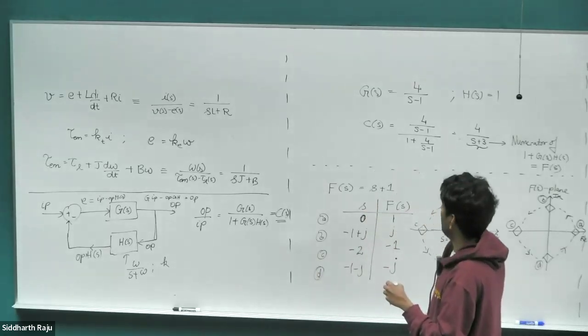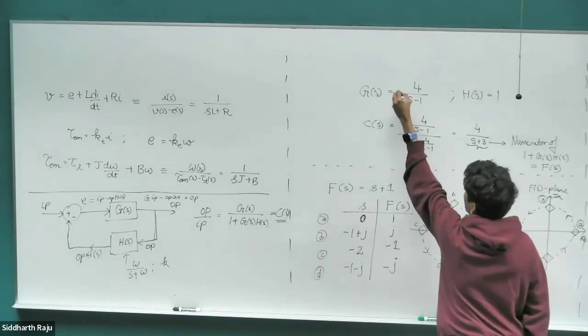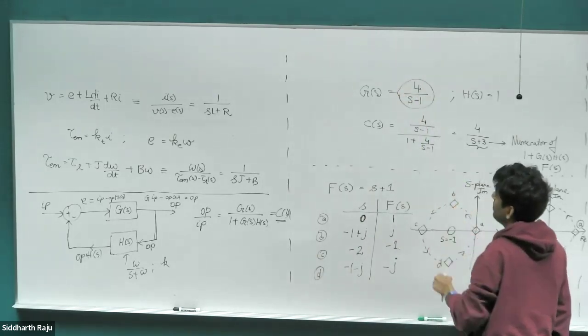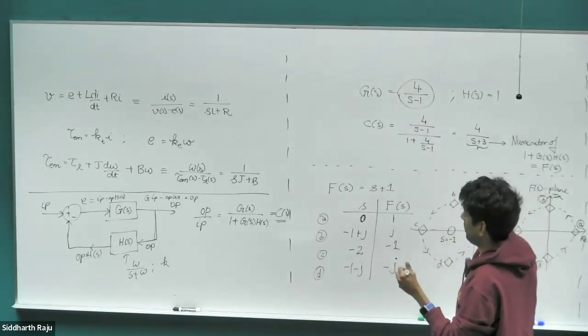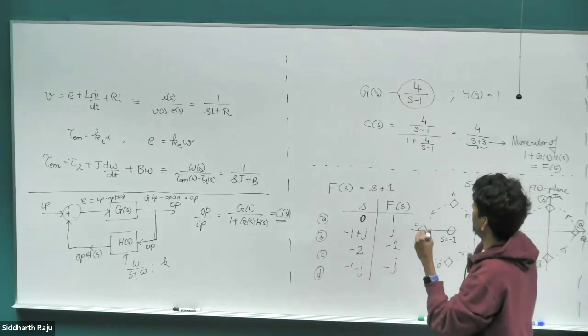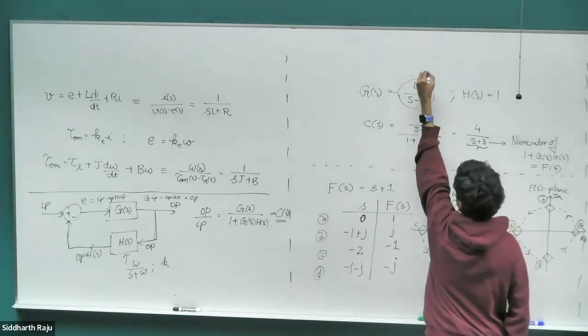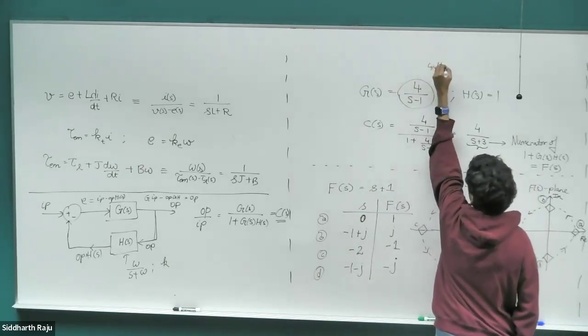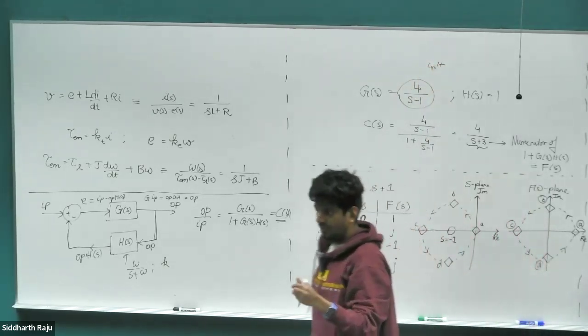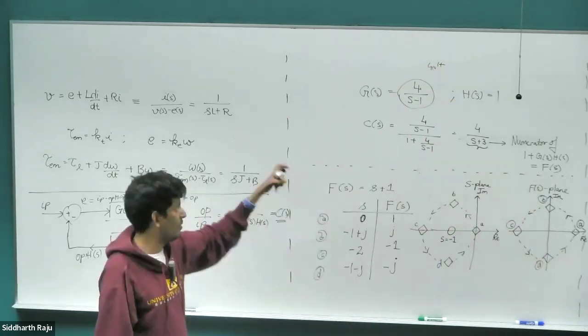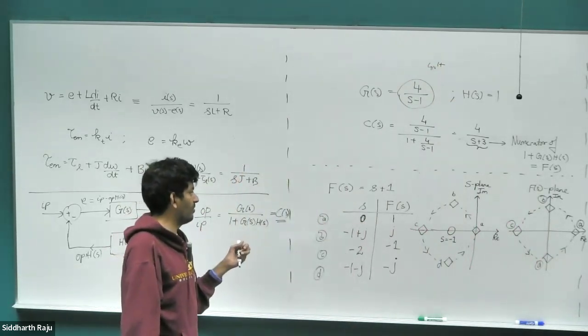And we saw that even if we have an unstable system, in this case we have an unstable system because we take the Laplace inverse of that for an impulse input. You would end up with e to the power of 1 times t. For an impulse input, the output will be e^t. So even though you gave a bounded input, the output will be unbounded in that case. So that's a completely unstable system.